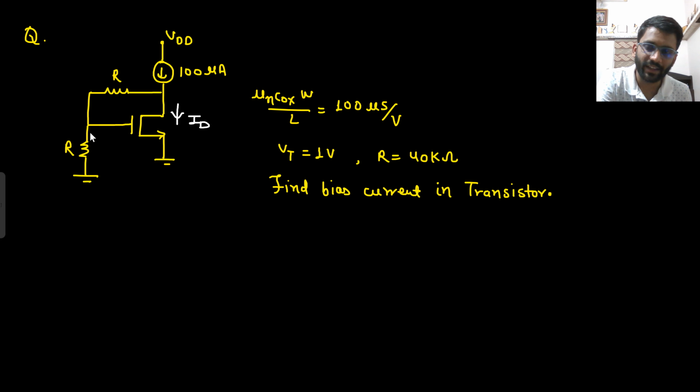It is true that here there will be 0 ampere current. But who said current cannot flow from here? Current can certainly flow from here. There will be no current here, but certainly the current can flow from here, right? So let us say this potential is V naught. Then what will this potential be? If this potential is V naught, this potential will be V naught by 2.